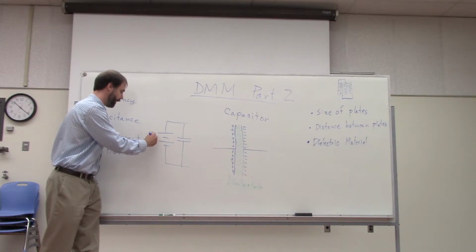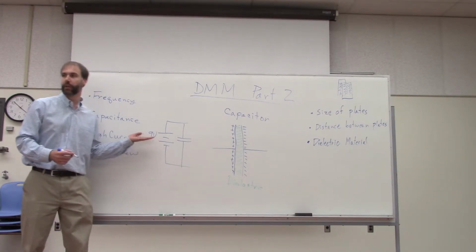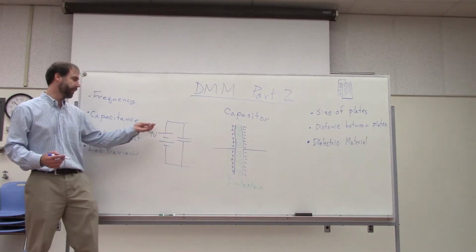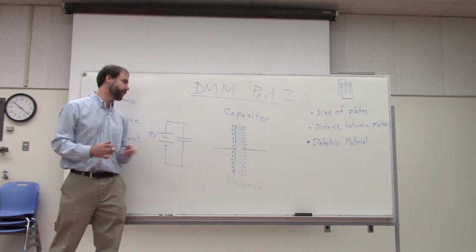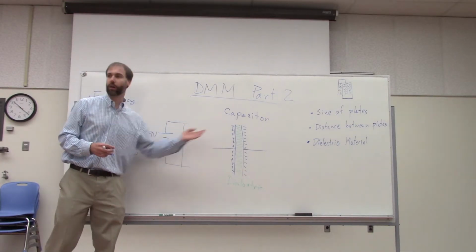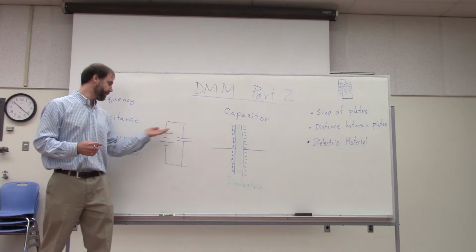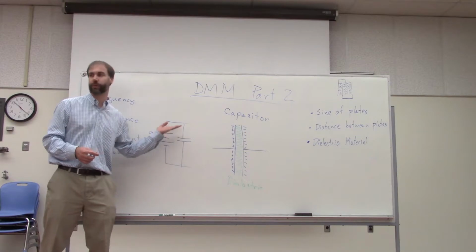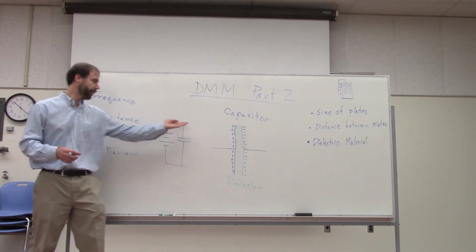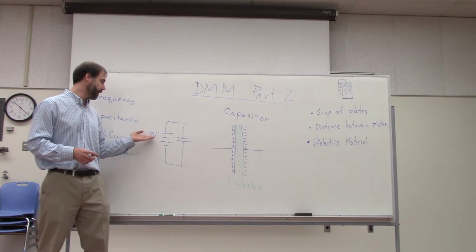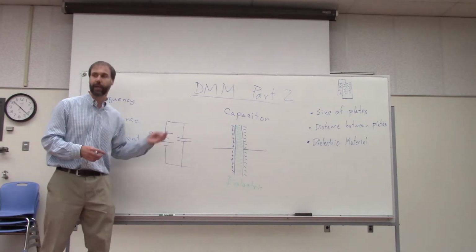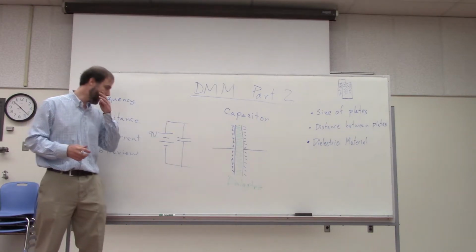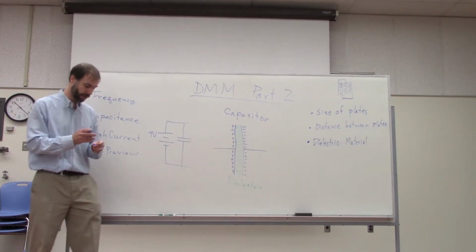So you had about a 9-volt source here. So this charges up the capacitor to 9 volts, and then when the rest of the circuit tries to draw a lot of current, that brings the voltage down a little bit, and it draws some of the energy out of the capacitor to supply that extra current. And then when less current is needed, the battery charges the capacitor back up again, and it's ready to be used the next time. So that's one application for capacitors, but there are others as well.